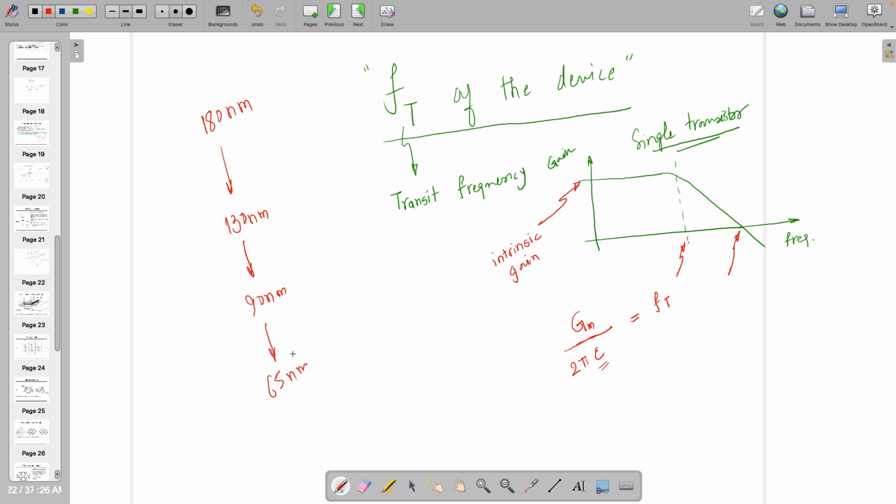Okay, so I made a mistake then. Capacitance is going down, right? No. There are two things, right? Epsilon A by D. So area is also getting decreased. Area is significantly decreasing compared to distance. So capacitance is going much lower, because for this case, if I am not wrong, 10 femtofarad is the capacitance of a single transistor. In this one, it was 2.5 femtofarad. These are numbers I'm writing for UMC or TSMC technology. These numbers are changing, so no need to remember them. The thing is, it's getting reduced.